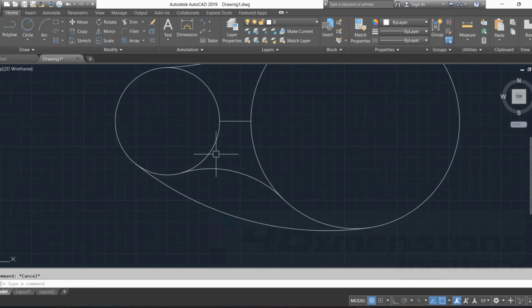So this arc is coming by selecting at the inner sides and the type is concave. And if we select the tangent radius at extreme ends, the arc is coming in the form of a convex shape. So this will be the difference if the selection is made in these two different ways, that is selecting inner sides or selecting outer sides.